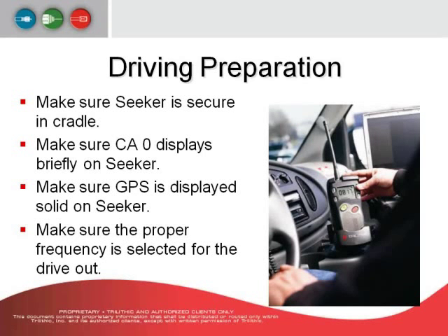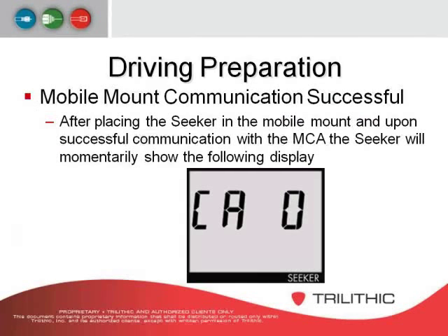And these are checks you want to do before you start driving around, because there is nothing worse than driving all day to find out that, wow, I did not have my leakage detector docked properly, because it's not going to pick up what you drove. And then you want to make sure that the proper frequency is selected for the drive out, because this is an agile leakage detector, so you can put in multiple frequencies, but you want to make sure that you're actually measuring the leakage frequency that is set up for that particular system.